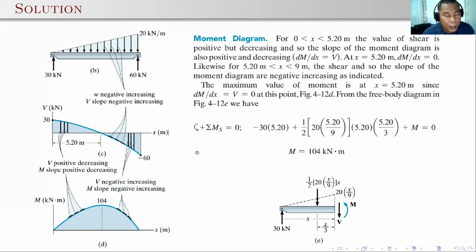So here, after drawing the shear diagram and determining the location of the zero shear, we expect that at this location the moment is maximum. So again, for the moment diagram, we need to plot first the moments at the left portion and the right portion of the diagram. Here, we don't have any moment, so we simply put 0 on the left and the right portion.